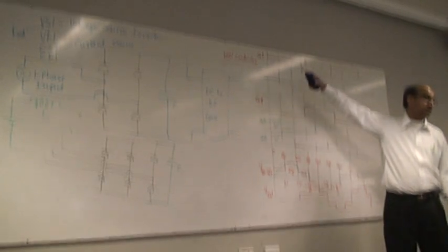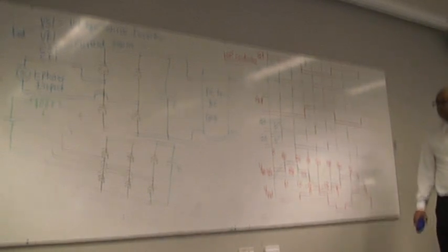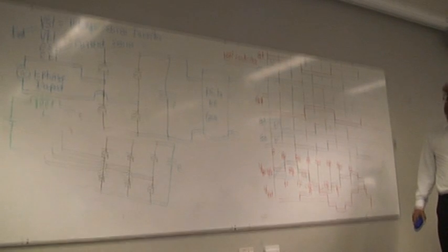What's the benefit of 120 versus 180? You get less voltage in terms of the output RMS value, but it gives you a much simpler control circuit. For 180 degree, as you can understand, there is always a chance that two transistors in the same leg conduct together. In 120 degree you can ensure that the short circuit path is fully eliminated, because there is no way you have the two transistors coming at the same time. That's one of the advantages.